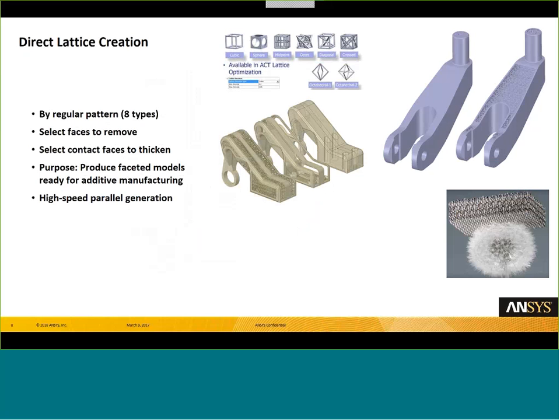Sure. In general, another overlooked feature of SpaceClaim is the fact that we work with not just full CAD geometry, but also faceted data. This is typically STL and OBJ formats that you are probably familiar with and have come across in the course of working with geometry. You can clean up and modify even these faceted formats as if they were the original CAD file that they probably came from. Now, as Roman said, we're always looking to extend the capabilities to make sure that we can either model and clean up things that maybe we weren't aware of before, new types of problems.